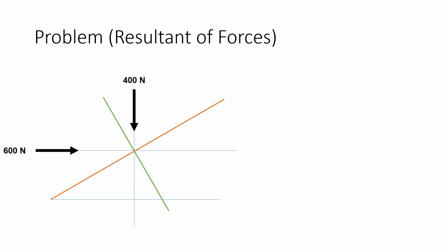So I have rotated the x axis and y axis by an inclination of 30 degrees. Why 30 degrees? Since with the horizontal plane the inclined plane is making an inclination of 30 degrees, that means the x and y axes are also making an inclination with respect to horizontal and vertical. The necessity of this rotation is to find out the inclination of the forces with respect to the rotated reference axes. If I am able to find out the inclination, then the resolution of the forces will be easy, and from those forces I can easily find my resultant of forces.